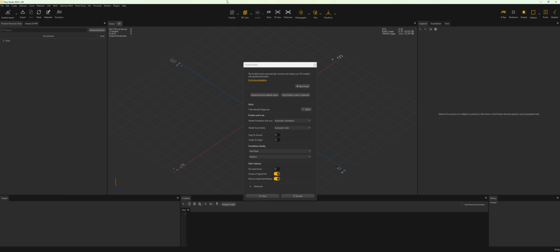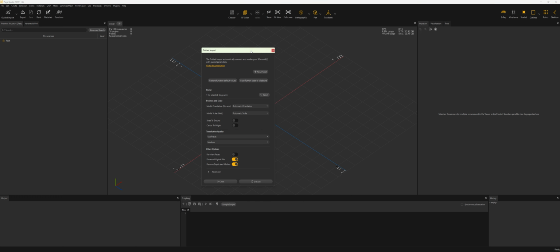But right now, we will do it the fastest way and basically the good way. So, first of all, what I need to do is change the custom values, let's say to 0.01. My max length will be like 10 millimeter. I think it was 10 or 12. This is based on the curvature, how many subdivisions we will get.